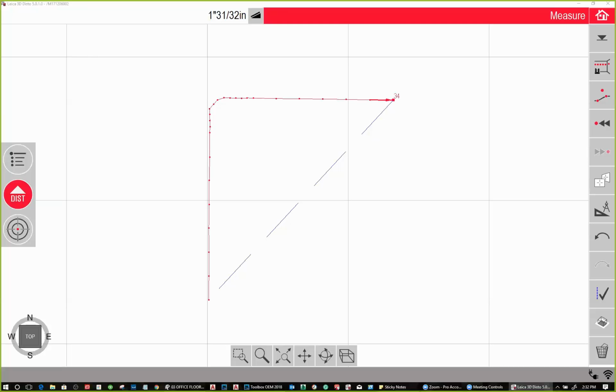You can measure those studs, but then you need to properly offset that 5/8 of an inch or whatever the sheetrock thickness is. And we found, if you're doing countertops, with the variations with the mud and the drywall that can happen, it's really best to do it after it's drywalled.